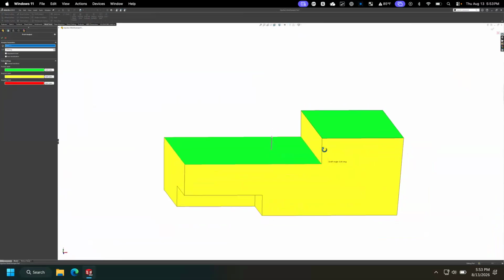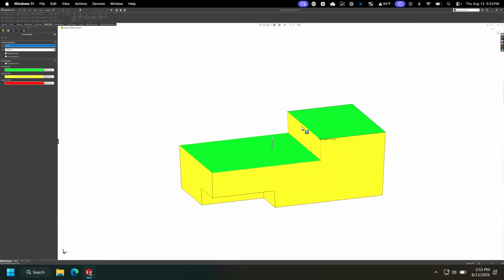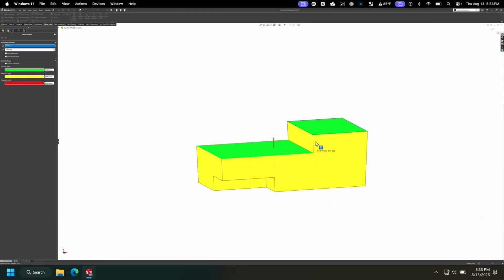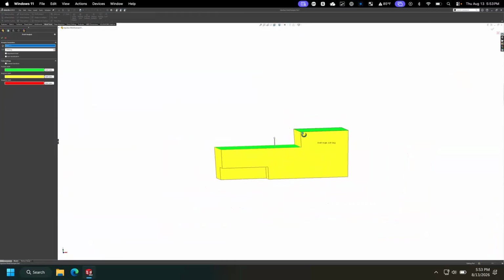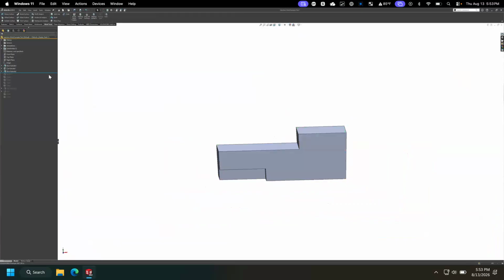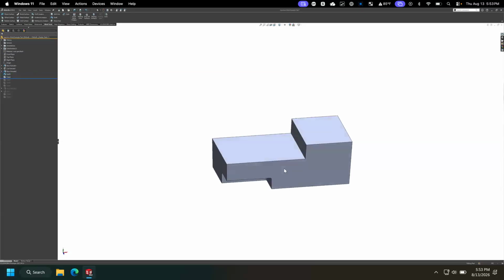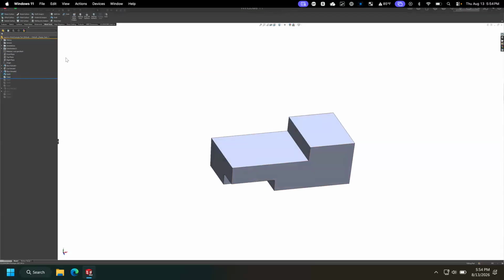You can see even from here, and we have a slide talking about it as well, but I'll touch on it now. We're getting that undercut there in our direction of pull because of the way it was modeled with the draft extruding up. So later, that's reverted with a secondary draft after the fact, and then we can do the shell.